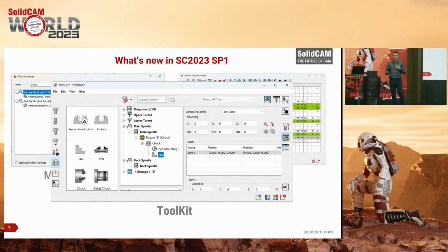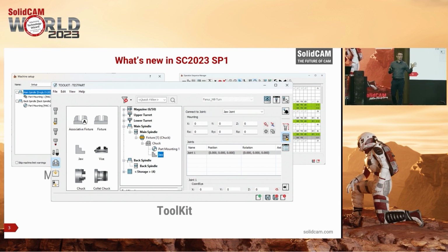As I was doing a lot of mill turns, Swiss type, going to the customer side, I was thinking how we can improve this. Let me just show you a little bit of something about 2022. Fixtures in 2022, you could always do it the way of associative fixture, where you have the 3D model in your CAD environment. In SolidCAM, you pick it up, that's your fixture. So this was like 3D model of fixture associativity. This was running great. We had two more options. One was the 3D parametric jaw, and it was 2D sketch jaw as well, right? So this was all supported in previous versions.